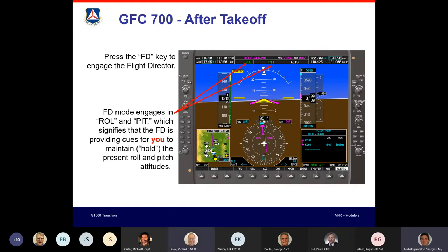You pull the autopilot breaker? Is that what you said? Yeah, because the autopilot breaker also is the electrical trim. So if you pull the autopilot breaker, you also disable the electrical trim, which is a good thing if you have a runaway trim. Yeah, I've been wondering about that ever since the 737 MAX fiasco. Yeah, we can disengage it here.